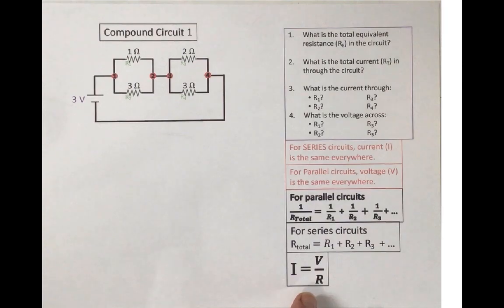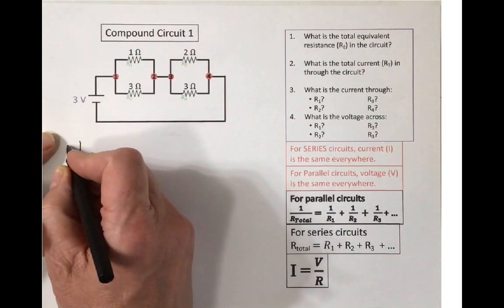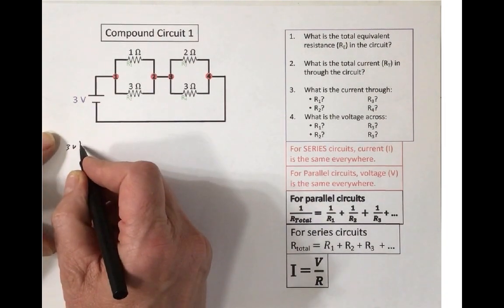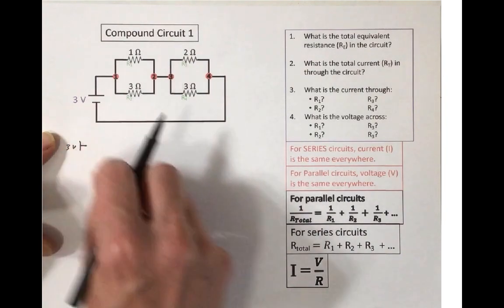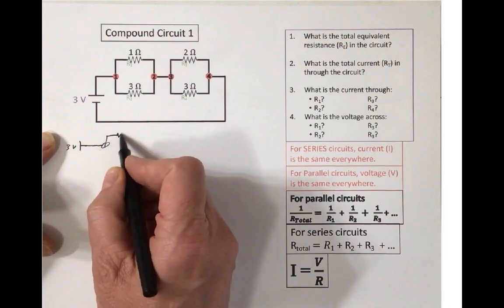Then we can use Ohm's law, go back up through our drawings, and use Ohm's law again to find the voltage and the current at every single resistor. So first thing we're going to do is redraw this as though we're in a line. So we're going to split the battery in half, and we get to junction 1 here, and there's a choice.